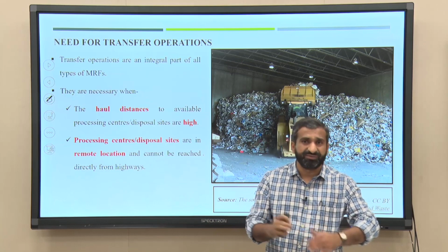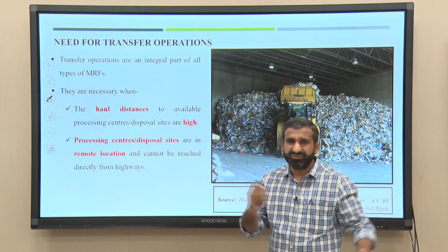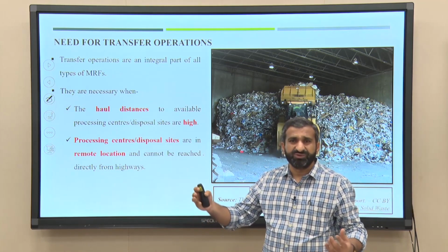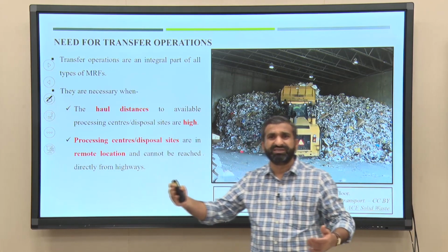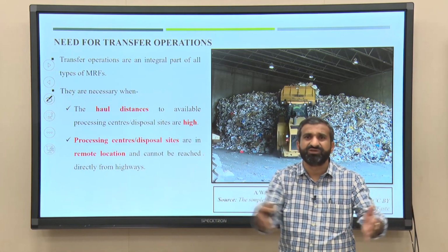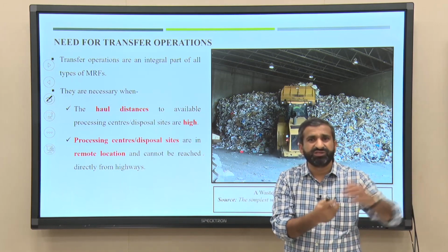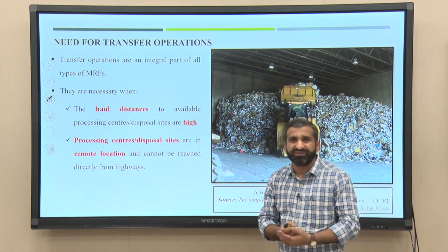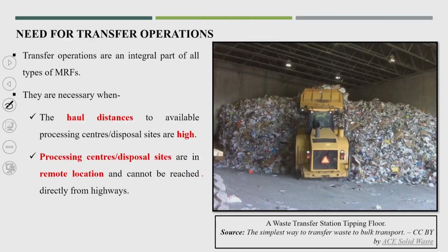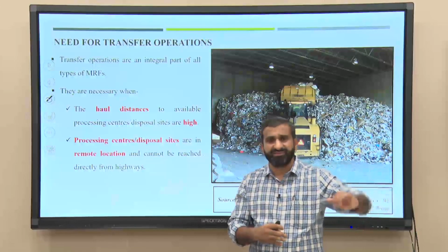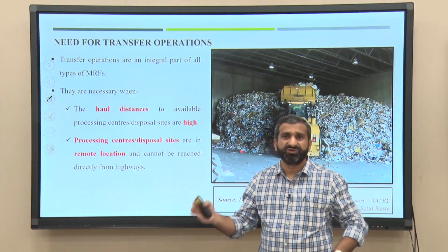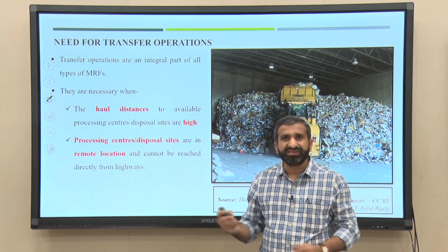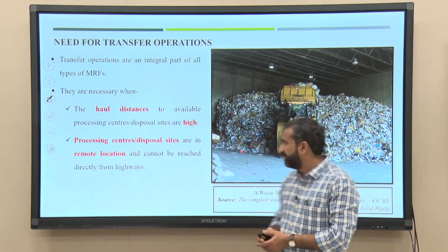And even if it is reachable by highways, it won't be economical to collect with small vehicles where only 2 tons, 3 tons of waste is transported on those roads and disposed into the disposal site or recycling facility. So, if in some remote location you are finalizing the recycling or disposal facility, in that case also, having transfer stations inside the cities will be very beneficial.